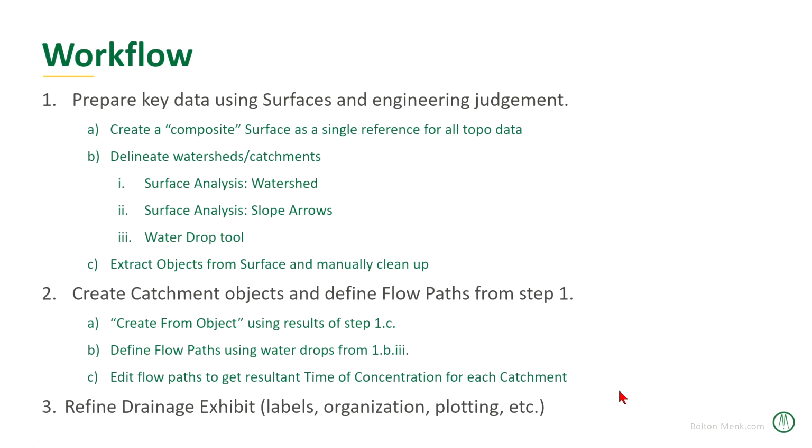And then lastly, we're going to edit our flow paths to make sure that our resultant time of concentration is valid and makes sense. And while we won't be actually exporting it today, that's a big part of using storm and sanitary analysis or the other Autodesk tools for your stormwater design, is that we don't have to transcribe all of that. But 1, 2, 3, let's hop inside the software and see how this is going to work.